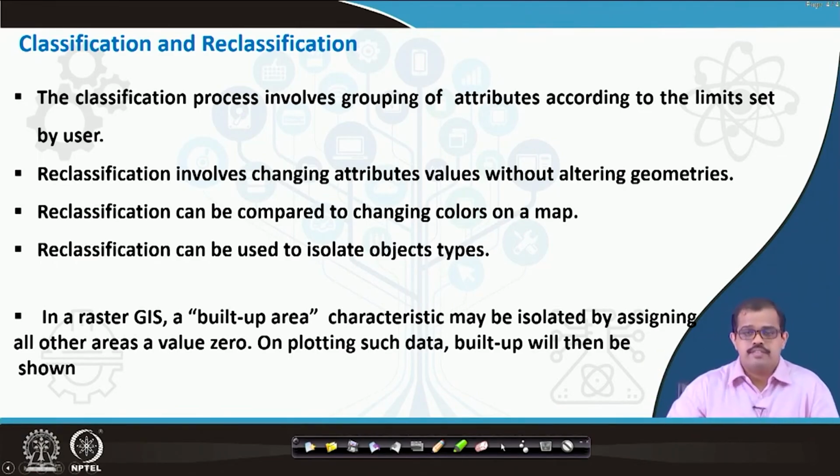Another way of classification in raster data is automating it using supervised or unsupervised classification. In supervised classification, a user gives the input in terms of signatures, which trains the classifier in terms of statistical significance, the statistical mean, standard deviation, variance, covariance, etc. Using all these values, the classification would happen.